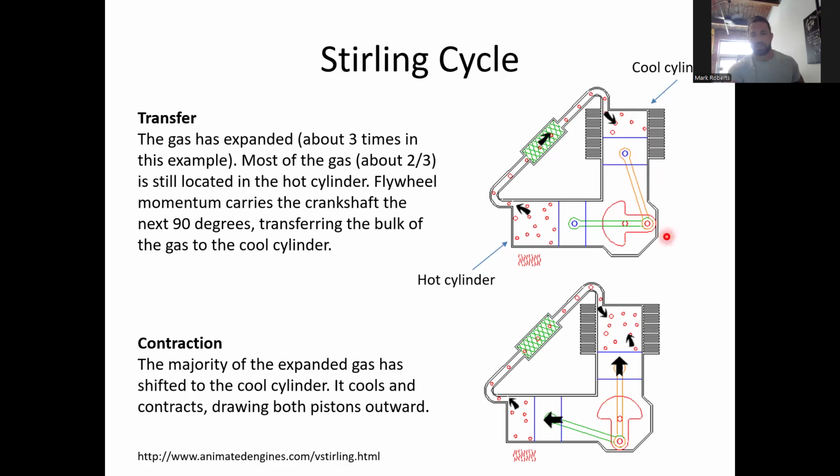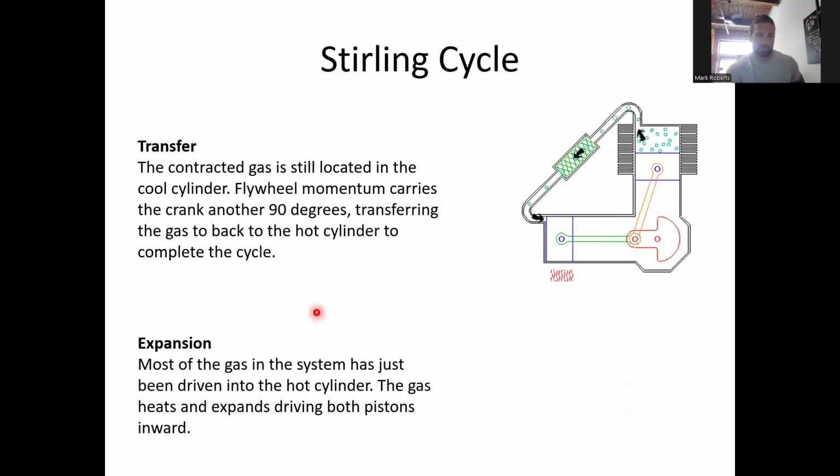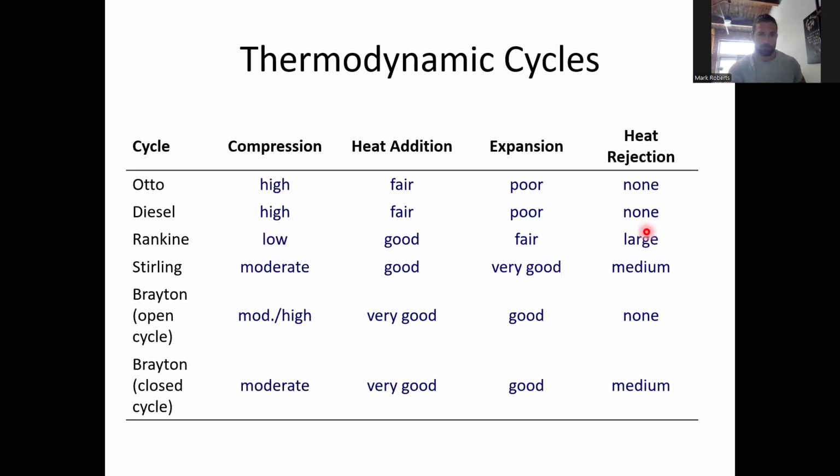Then on the cold side, the gas will contract. This hot gas on the cold side will reject heat to the cold side. And as these pistons are moving along this axis, the axis is helping do some of the work for the process. The axis has a specific design that allows this process to work as the gas is heated up, moved, cooled down, moved, heated up, and so on.